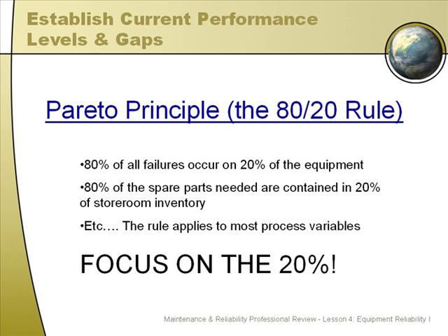So let's cut it one more time. Take 20% of the 2,000, and now you're down to 400 pieces of equipment. Well, 400 pieces is a little bit more manageable, but still a little bit thick. So let's cut it to 20% of 400. Now you're down to 80 pieces of equipment. 80, you can fit that on one piece of paper. So take those 80 pieces of equipment and rank them from highest to lowest and start working on making those 80 pieces of equipment as reliable as possible. They're the big 80 hitters in your group. They're the 80 most expensive pieces of equipment in your facility.